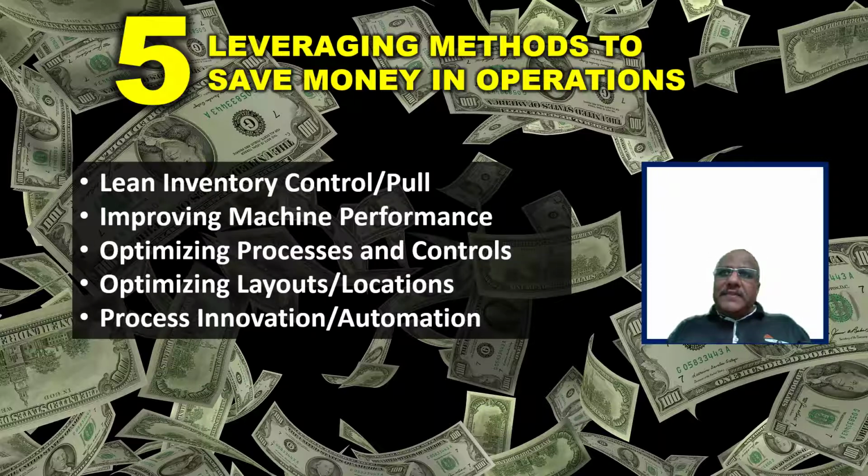Now, there are 5 methods I'm going to tell you today. First is lean inventory control. Lean inventory control can be done in the shop floor and even in the entire supply chain. Second is improving machine performances so that you do not have the waste of waiting. Third is optimizing process controls. This will lead to quality improvements. Fourth is optimizing layouts or even locations. We can bring machines nearer together, processes nearer together, or maybe even factories strategically nearer together in an entire supply chain. And the last thing is process innovation, which could also be coupled with automation.